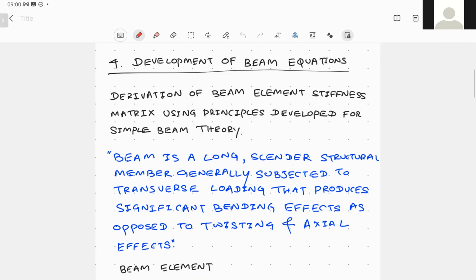That is, you first construct the element stiffness matrices, then you develop the global stiffness matrices, apply the boundary conditions, and solve for the unknowns, applying the compatibility conditions. You can access the reaction forces, or depending on the problem, the required parameters. So it is the same concept.